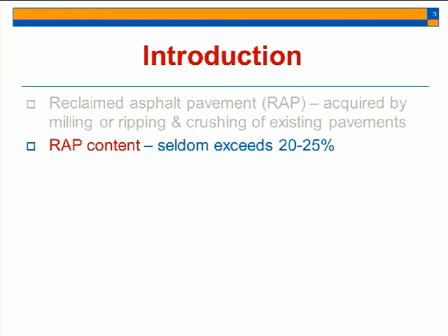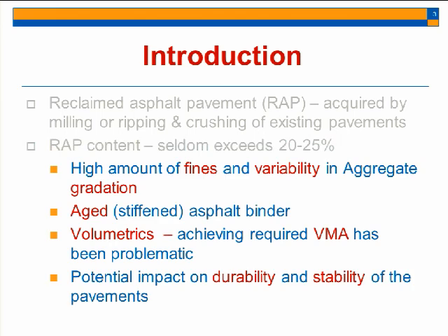This is due to a few reasons. One of them is the introduction of a high amount of fines and the variability in aggregate gradation, which is introduced by RAP. Then the aged asphalt binder is also one of the key problems which RAP brings into the mixtures. Due to the variability in aggregate gradation and fines, researchers have faced a lot of problems in achieving the required volumetrics for these mixtures.